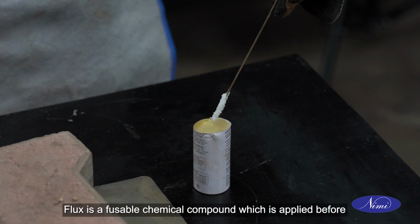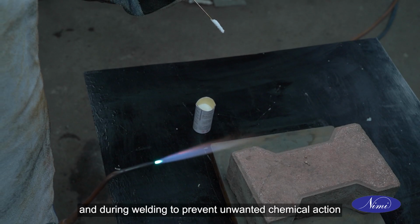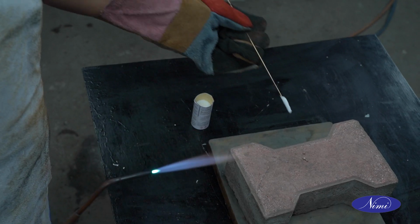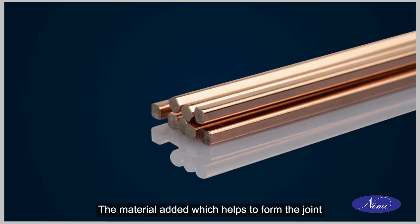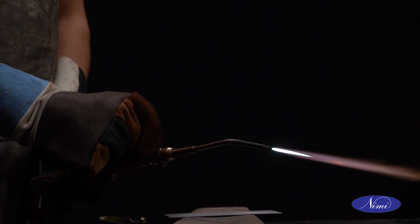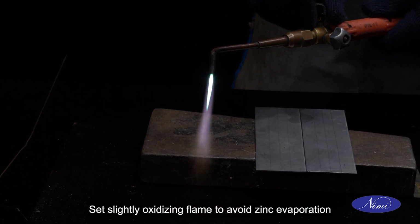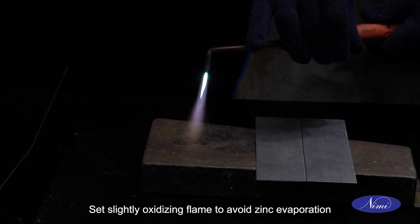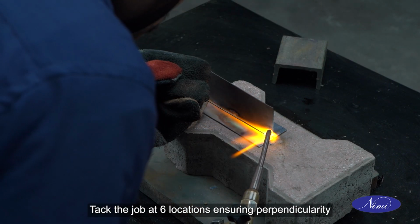Flux is a fusible chemical compound which is applied before and during welding to prevent unwanted chemical action. Borax is a flux used. The material added which helps to form the joint is called filler or consumable. Ignite the torch using spark lighter. Set slightly oxidizing flame to avoid zinc evaporation. Tack the job at 6 locations, ensuring perpendicularity.